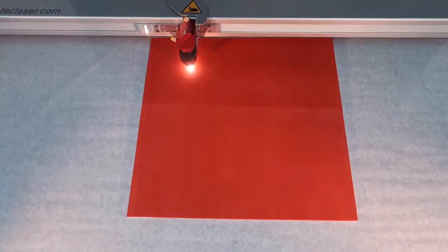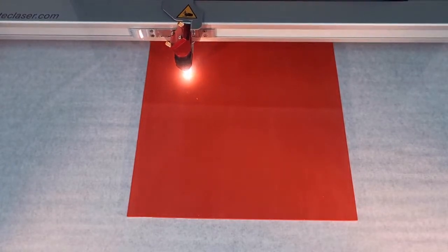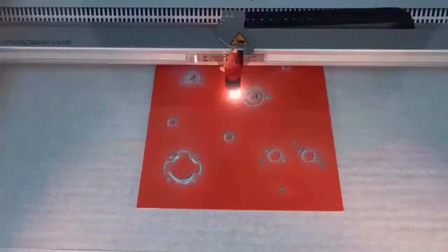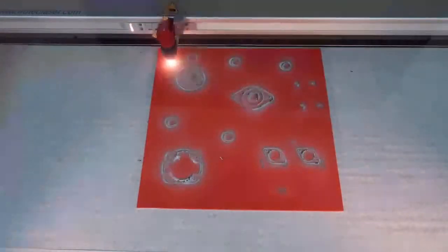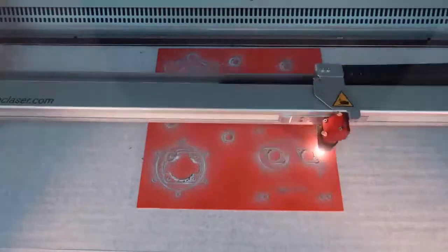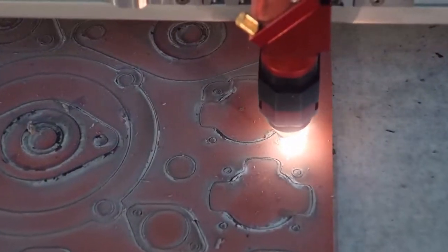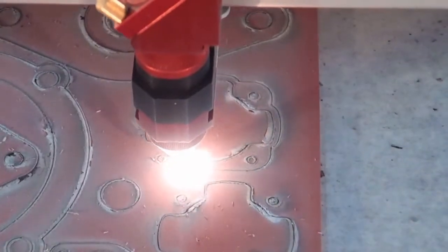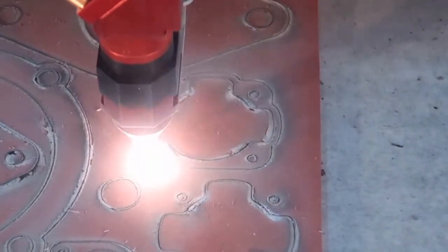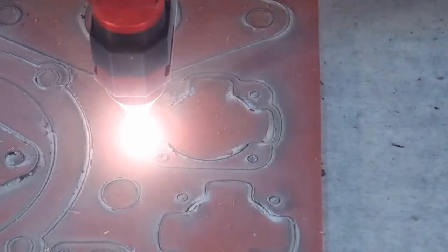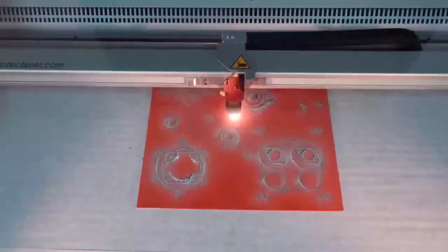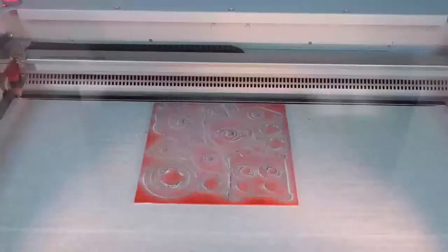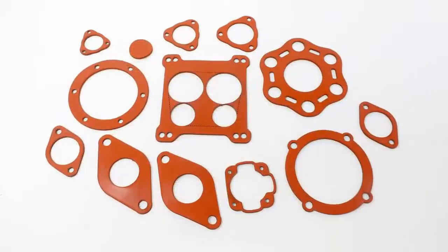Here's an example of cutting just your standard off-the-shelf silicone-based rubber. You can see the flare that comes from it, the carbon dust that forms around the edge. This is not rubber stamp material. This is industrial, engineering-based silicone rubber, but you can see the carbon that comes off of it. This is why the air assist and the cutting table are necessary. And we're cutting a whole bunch of sheets of gasket or spacers in this case.